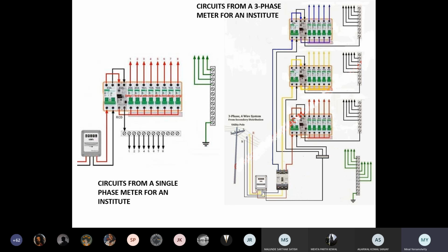Now this is not the cutout fuse. Okay. Cutout fuse will be before the incoming line. This is the outgoing line which will have the fuse to protect the line going from the meter to your area. Okay. So now imagine this is travelling, so this fuse will be in the meter, okay, it goes to the bus bar and it gets distributed into these various lines, and each red line is then taken up via conduit to your place, okay. This was in a single, say, a small building or a small house or a small bungalow. This is possible. In a flat, the second diagram works.